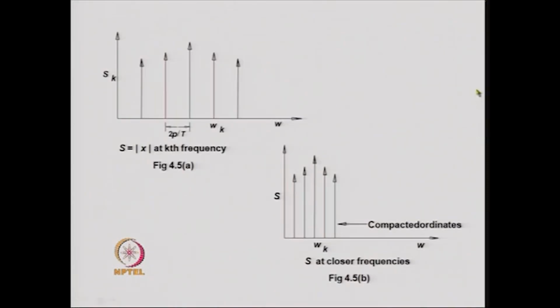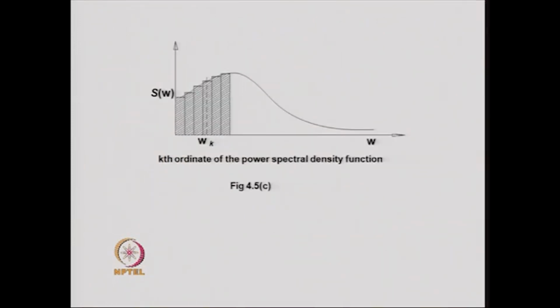Now, how we obtain the power spectral density function curve that I described before. If you can have the FFTs of the time histories and plot the amplitude squares in close enough range and then divide by d omega, then these are the different bars, and you will have N/2 plus 1 number of bars.